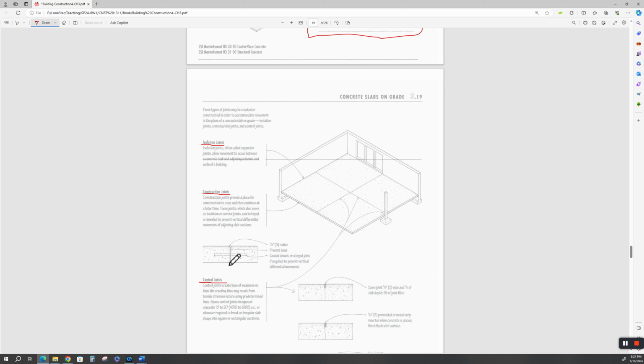The rods will be greased, and there'll be a can over here, and it allows the pavement to expand and contract. And then there'll be a compression board. He calls it a prevent bond in that joint. That's okay for a roadway, but for a slab, you really would like it keyed so it can move this way, and it helps with mitigation.